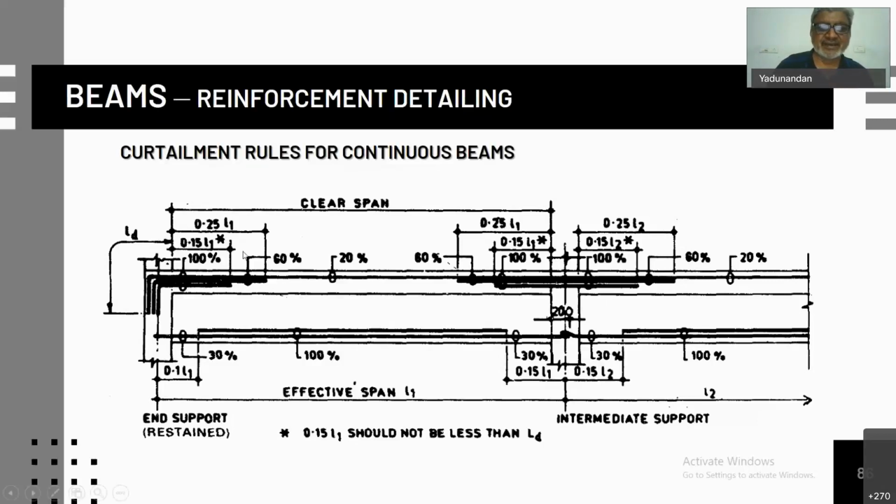So, in a similar way as the slabs, we provide top bars, and bottom bars are normally provided in layers. You can see only 50% or 30% of the reinforcement can go from support to support. Whatever reinforcement you have to provide at the center for positive moment can be curtailed when you go near the support, and we can provide the negative reinforcement at the intermediate points at a distance of 0.3L or 0.25L, and only provide hanger bars for the shear stirrups to be suspended in between.